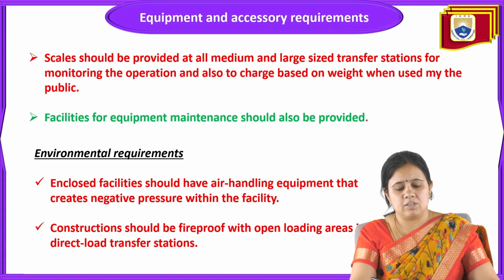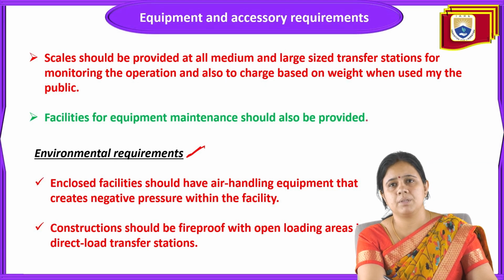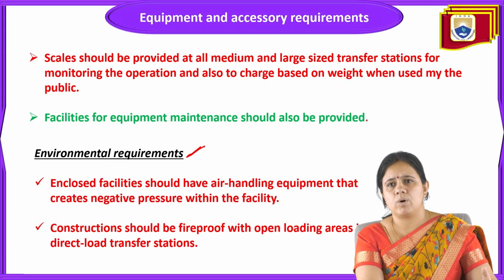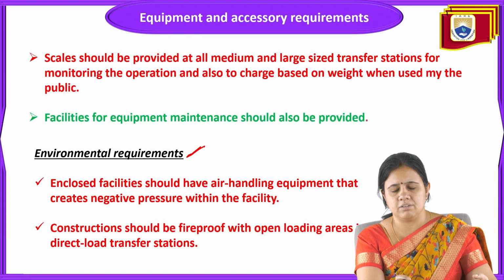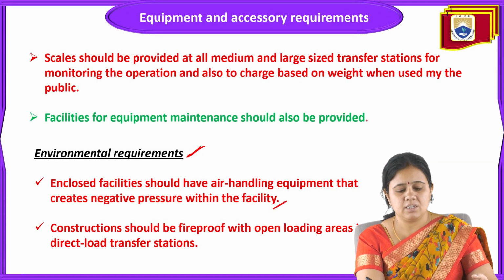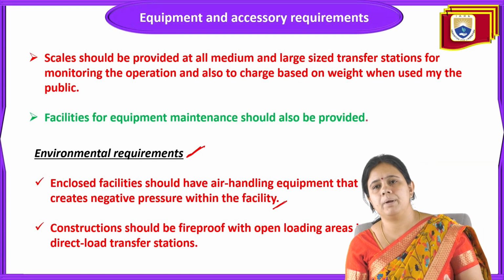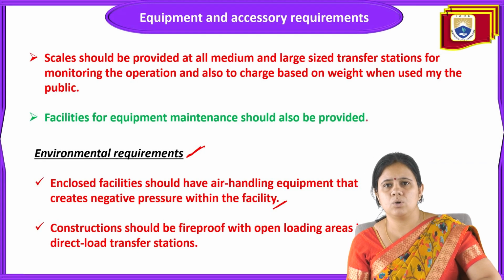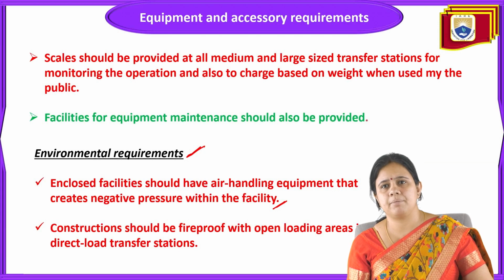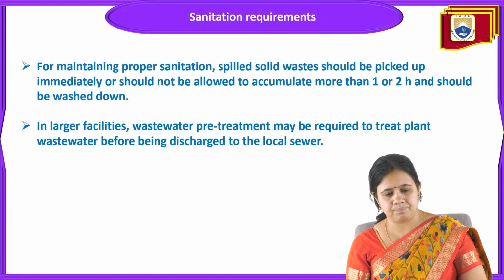Environmental requirements: from the environmental point of view, the enclosed facility should have air handling equipment that creates negative pressure within the facility. Construction should be fireproof, with open loading areas in a direct load transfer station.